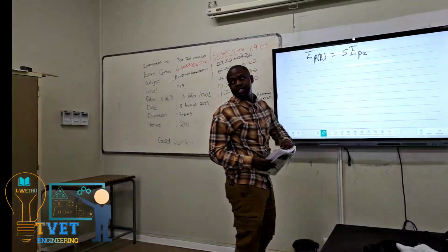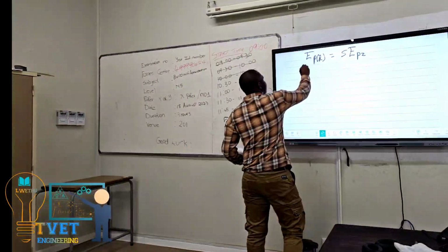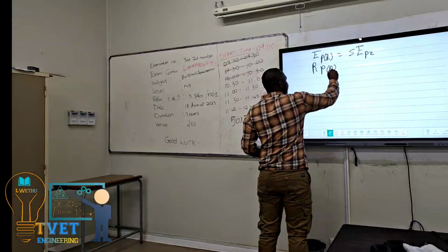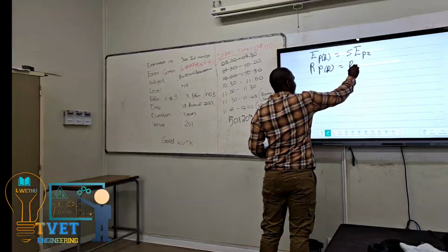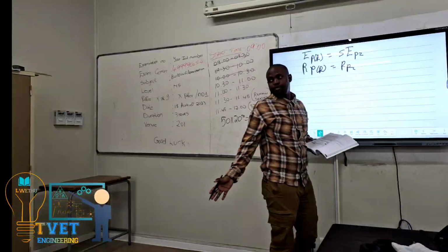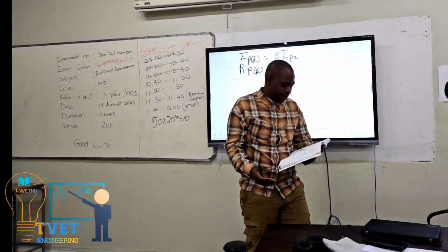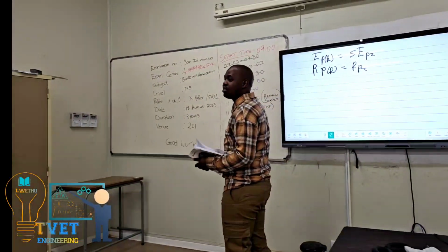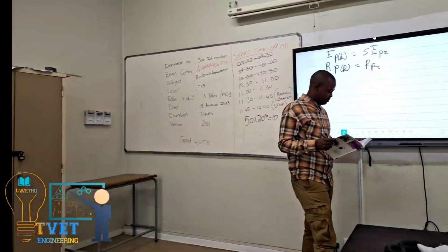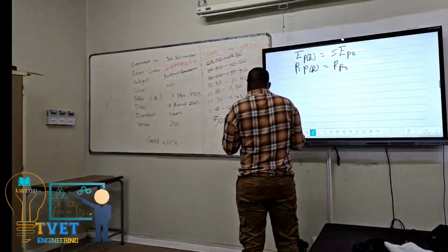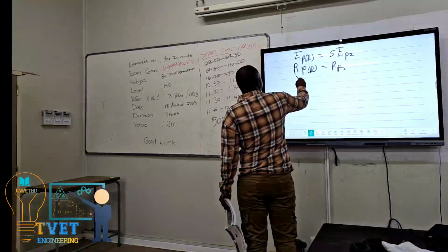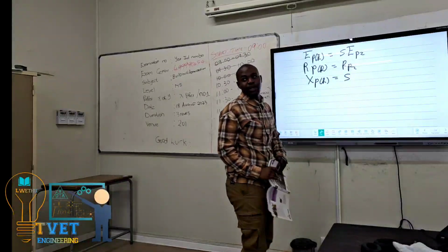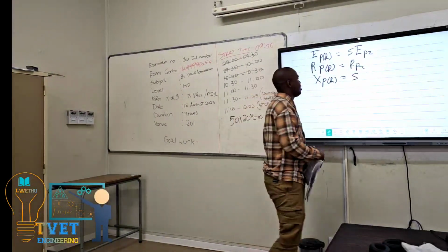Notice the resistance does not change. It is still equal to R2 because it is not frequency dependent. Your reactance is frequency dependent, so we multiply it by the slip.